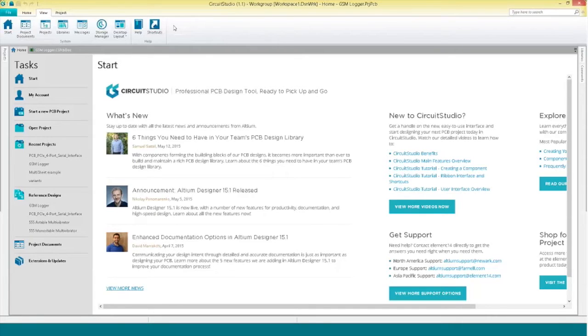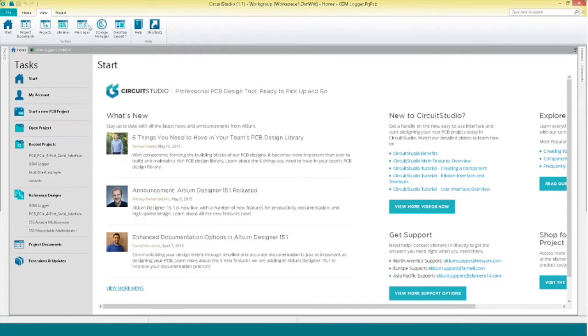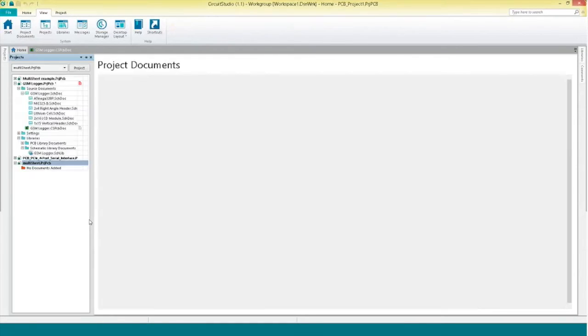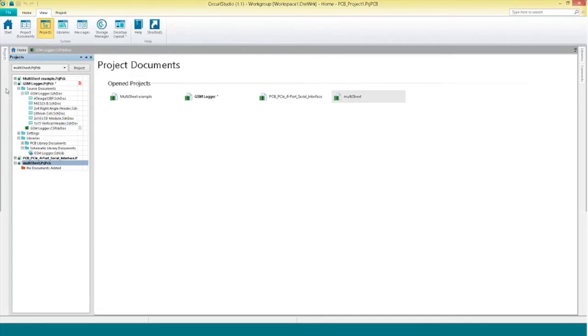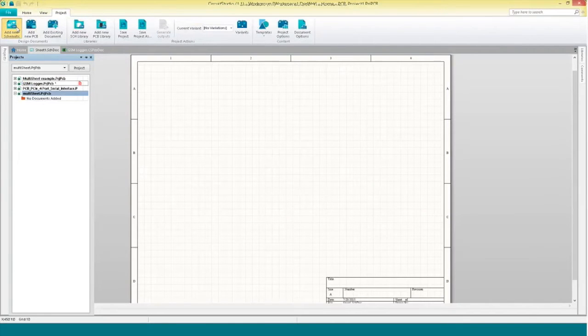We'll go ahead and look at some connectivity and multi-sheet designs here. We'll take a look at a flat design and a hierarchical one, and a little bit about the inspector panel. Let me go ahead and create a new project here. And then I'll add a couple new schematics to that project. Just from my project menu, add new schematic. I'll put about 3 of them in here.